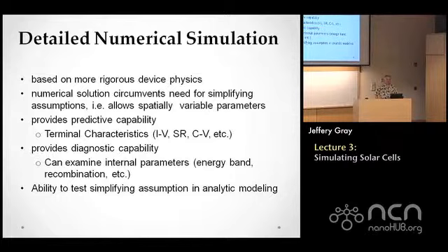But detailed numerical simulation is based on much more rigorous device physics. I think Professor Lundstrom showed you the semiconductor equations: Poisson's equation and the continuity equations. So we're going to solve those equations making as few simplifying assumptions as possible, which means we're going to need the computer to do that. And if you can do that, then you can generate everything that we did with the analytic models, but without having to make the same simplifying assumptions.